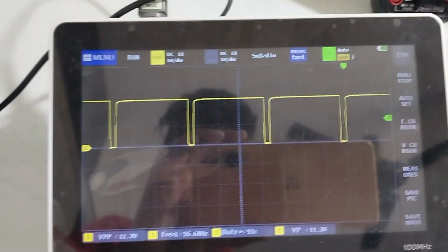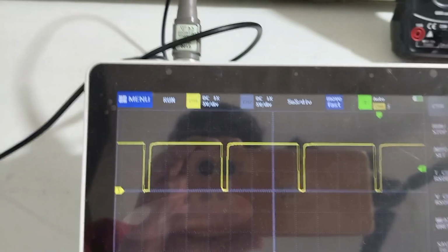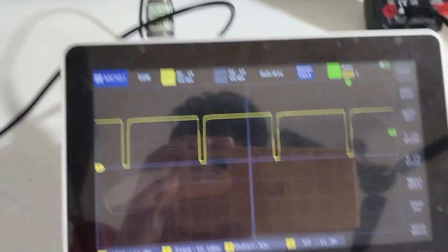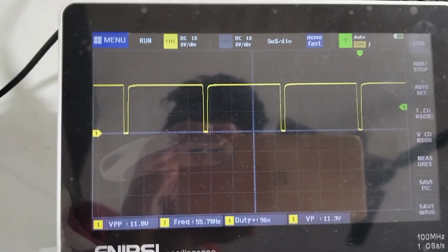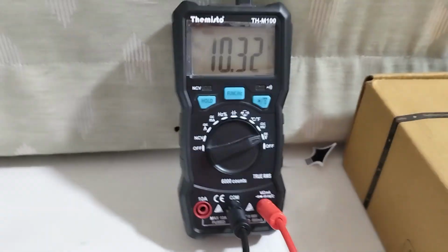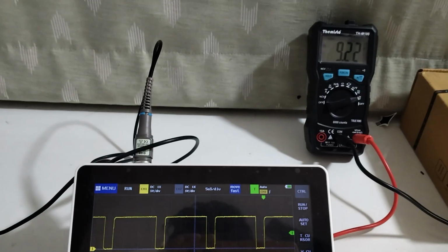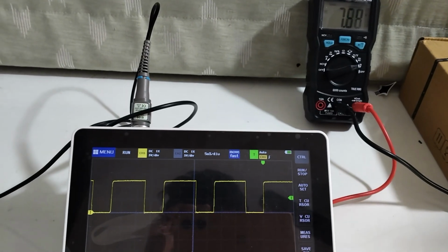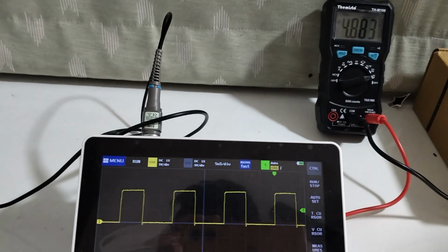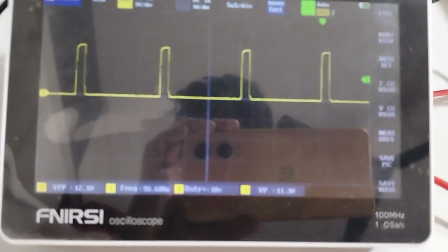On the other hand, for a boost converter, it's very dangerous to go to 100% duty, so we try and limit it to maybe 85% or so. But here it shouldn't be a problem. Now we're at about 95%, and you can see we have 10.3 volts, which, considering we're doing this on a breadboard, is very nice. Now we can even reduce it. Let's go back, and you can see the output is dropping again since I'm decreasing the duty cycle. Let's go back to the minimum. We have 10% duty again as before, and the same 1.1 volt output.